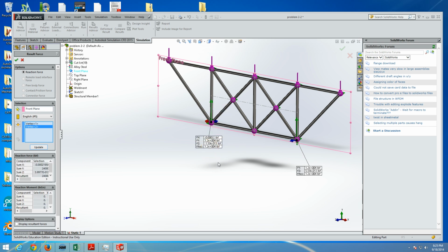Okay, so the only real resultant force should be vertical. And what is this? 12,000 pounds, 1.2 E plus 4 pounds, in the vertical direction. Here, 1.2 times 10 to the fourth, so 12,000 pounds, evenly distributed. This was an obvious case that it will be evenly distributed because the model was fully symmetric.